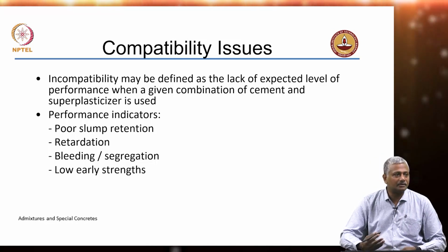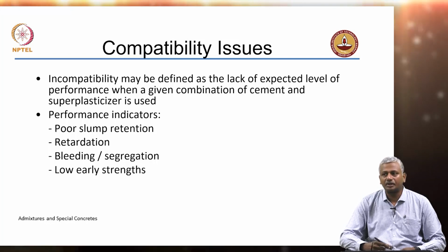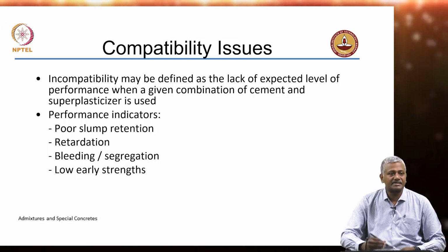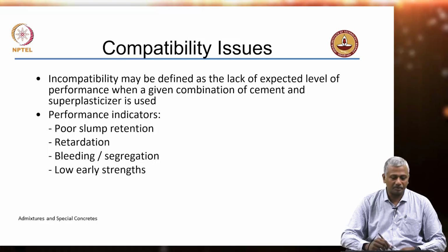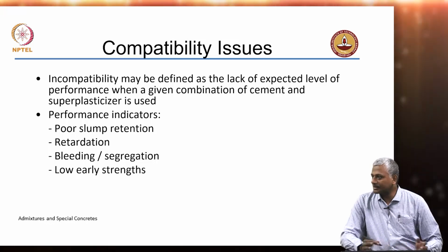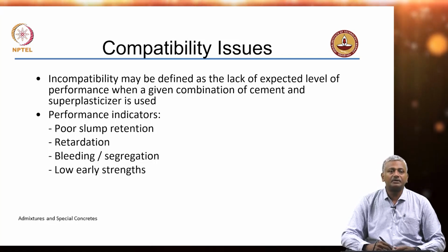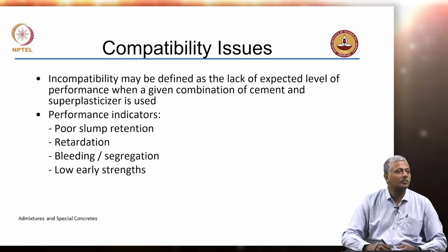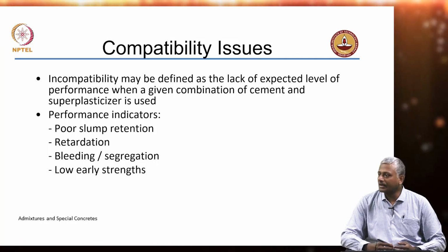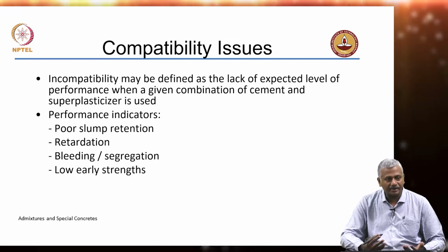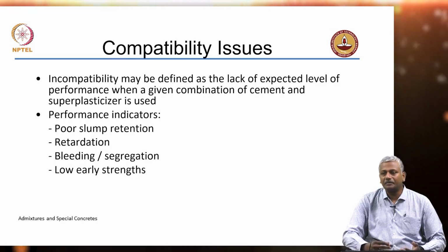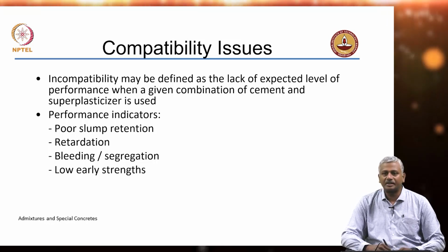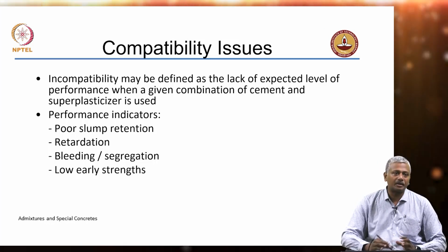You have to decide or design your concrete mixture appropriately to avoid this effect, and this effect could be exacerbated when you have a chemical admixture in the mix. Okay. Low early strengths, another issue. We often design concretes to obtain high early strengths. We want to open up the structure early. We want to carry out the work in a fast track manner and for that attainment of early strengths is very important. So, when you do not get early strength, that is basically a sign of something wrong in the chemical system.